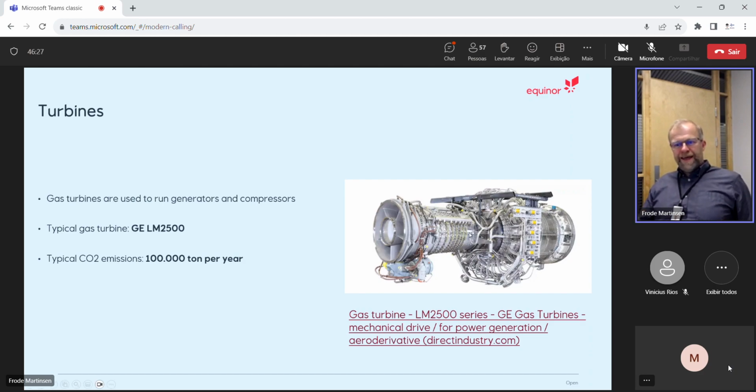So if you want to increase the efficiency, you'll actually have to take out the energy in the exhaust. Typically easy to do onshore, but the exhaust is only heat. It's low quality energy, so you need huge equipment to be able to take it out. And offshore, typically weight and space constrained, it can be quite hard, but there are attempts to do that. You can put a steam facility in the exhaust pipeline and use a steam circuit to create additional electric energy and increase the overall efficiency of the system.